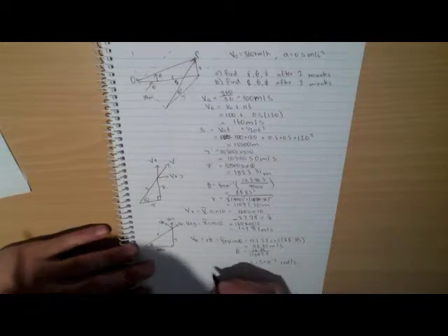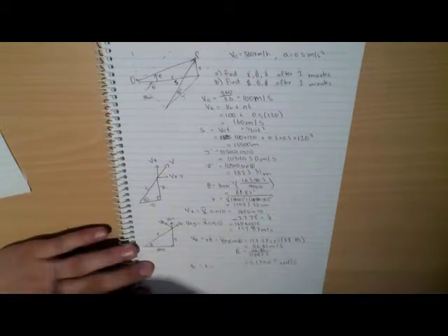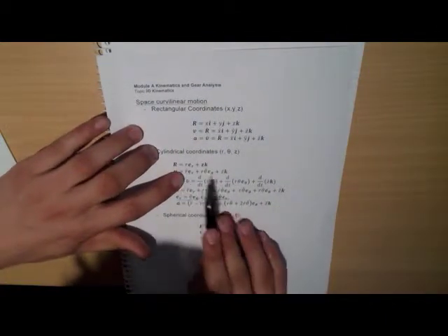We can also work out R dot, because we know VR is equal to R dot. Again, from these equations we have VR equal to R dot and V theta equals R theta dot, which is where I got this from before. So we have VR equals R dot is equal to Vxy sine theta. So this is going to be equal to 157.57 cos 68.85, which is going to be equal to 146.96. So therefore we have R dot is equal to 146.96.